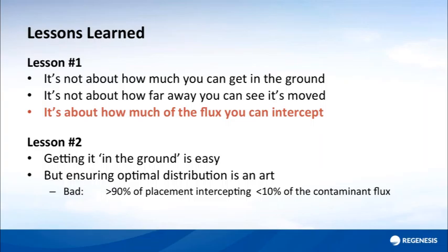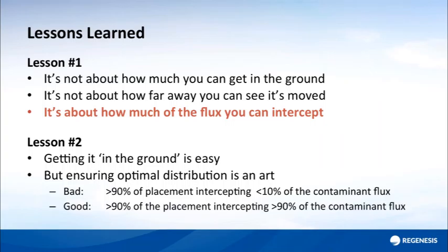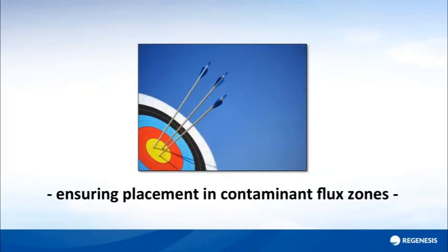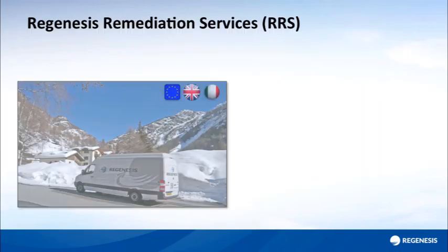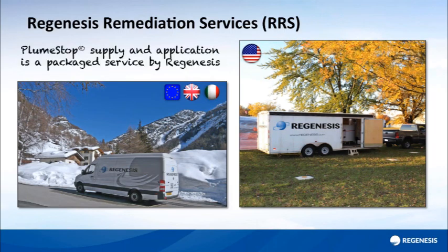And so, ensuring how we do this in practice, one of the lessons that we've learned is essentially that, rather than sell the material, at least for the time being, we're applying PlumeStop directly ourselves using our own kit and being sure that we are targeting those flux channels. We have our equipment across the States, we have equipment across Europe for these applications. What we will typically do ahead of any of the injection work is take a good look at the aquifer itself, the main flux channels, etc., and we'll do a flux zone verification exploration ahead of the application of the PlumeStop.